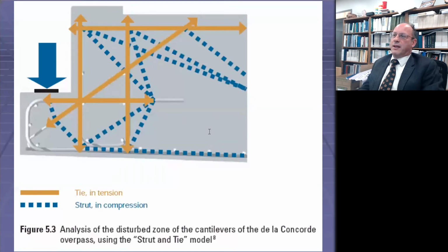You can also look at this from the standpoint of analyzing it with a strut and tie model. And this came out of, again, the investigation report, of how you then have your ties in tension to carry the force. But you see that that diagonal tie has got to somehow connect and transfer force to that top horizontal large bar if you're going to provide that strength.